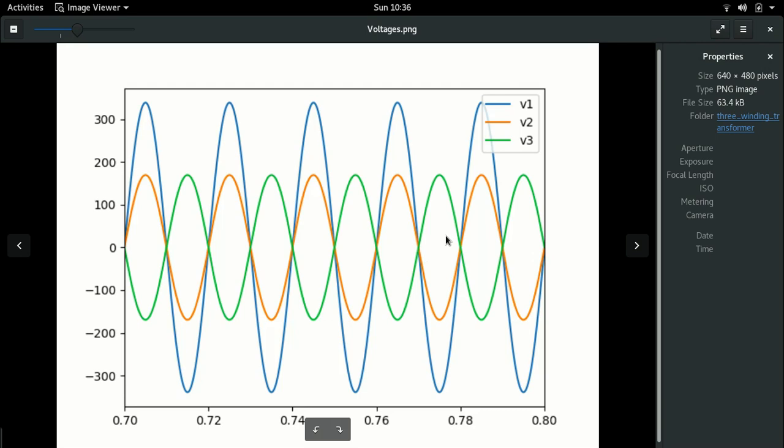So with this, now that we have this transformer running at 50 Hz, the next step is to have this running at high frequency. Now, typically, the frequencies we are looking at, especially for a forward converter or for a flyback or any other kind of DC to DC converter, is usually in the range of around 20 kHz to around 50 kHz. That is the usual range.